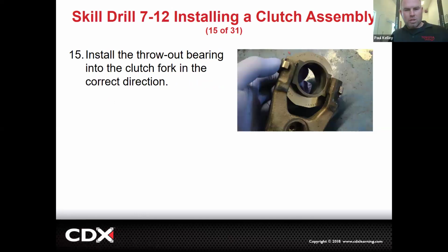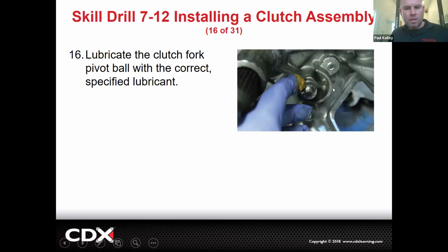And then once you go to install the transmission, it'll slide right in because it was centered, okay? But additionally, we're going to change that release bearing. They might call for grease in certain points. It might call for that spring. If it's got a spring, replace it now.